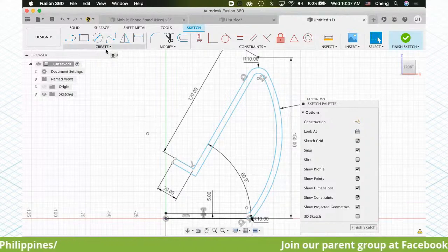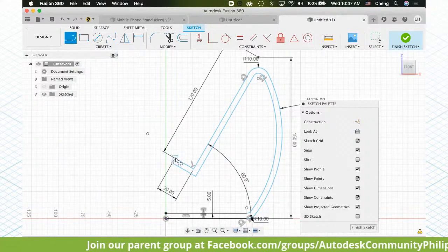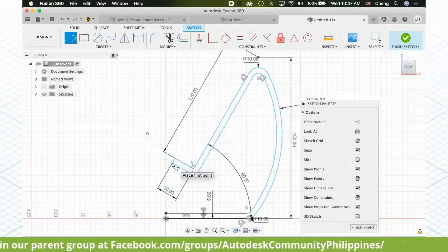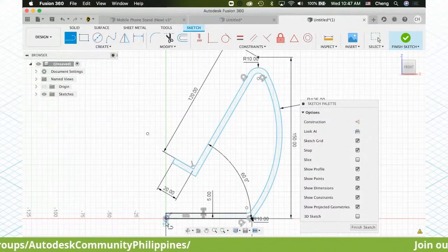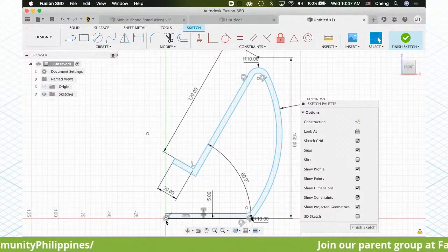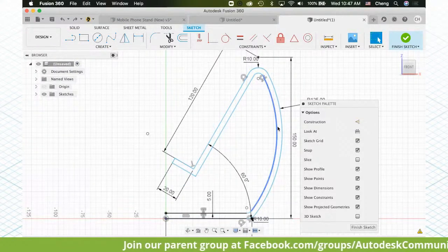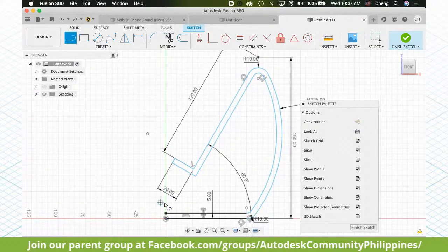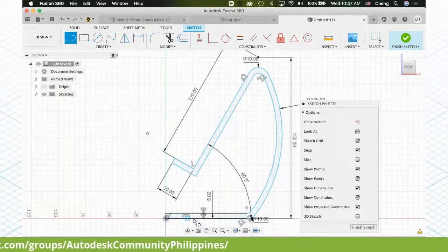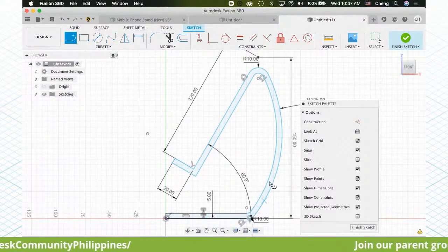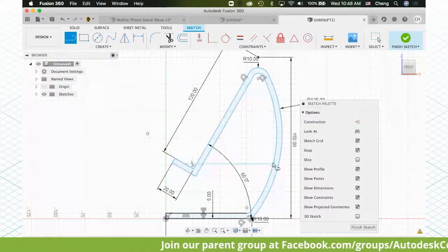So in the extrusions, it says we need to do a close gap. So I just do a simple close-up gap to the edges. 1, 2. Before we do a close-up gap, you notice that the screen is not shown in a transparent white color. But once I do a close-up gap, what happened? You see the screen right now has turned into a light blue indication to show me that this is a closed loop.